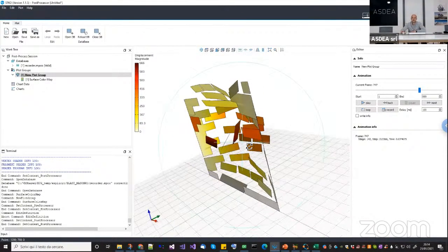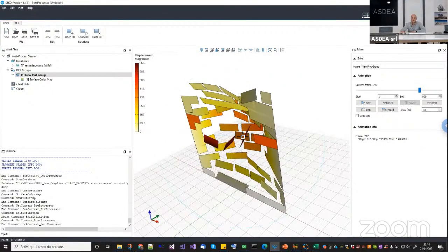In static problems, of course, it is singular, okay? Because you only have the stiffness matrix. That matrix is unconstrained, so the stiffness matrix has 0 eigenvalues, and the problem is unstable. In dynamics, you don't only have the stiffness, you also have the mass, and so you also have mass on these elements. So in dynamics, you can simulate something that actually falls down, okay?